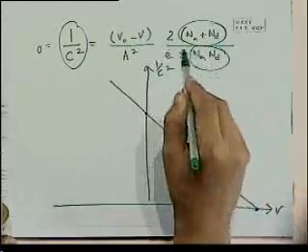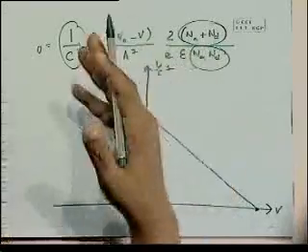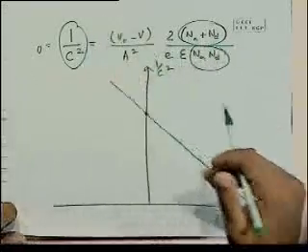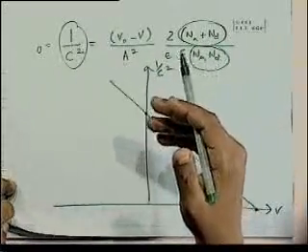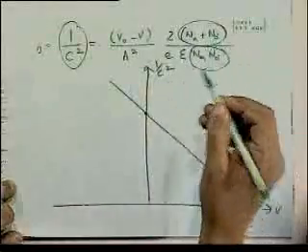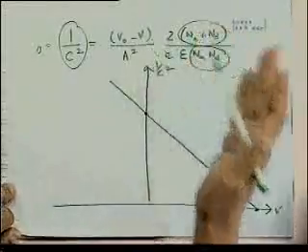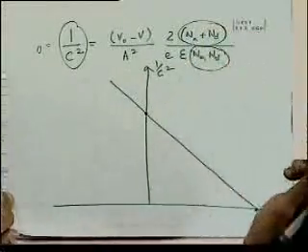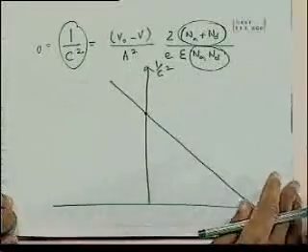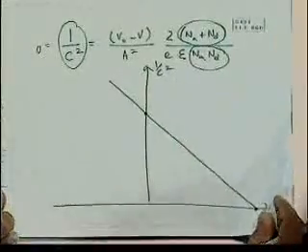If one is larger than the other, so you've got a P plus N type of junction, or even for a Schottky junction, you can plot this and you would get the value of either N_A or N_D. If it's a Schottky on an N type, we will get the value of N_D. If it is P plus N, we will also get the value of N_D. So this is a very useful technique that we can make use of to determine the parameters of the particular diode that we are studying.